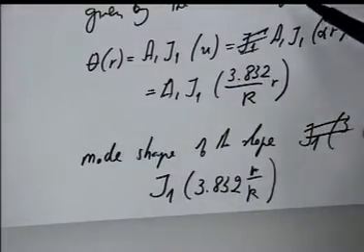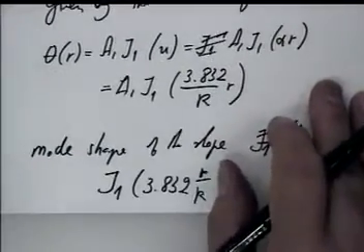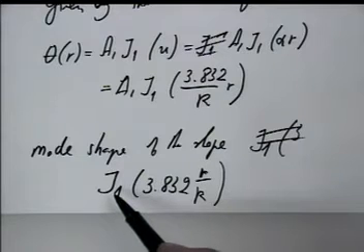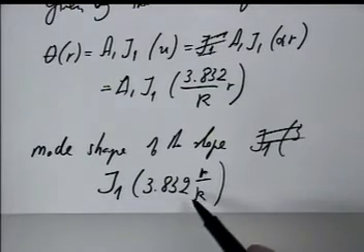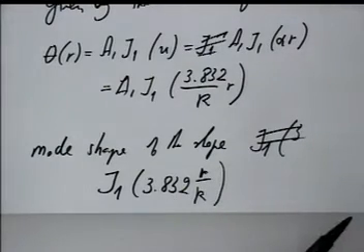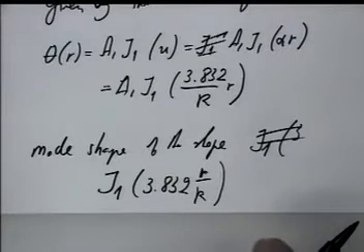So, mode shape is given as a transcendental function because that is an infinite series. For evaluating at any point, you should have an infinite series. We can actually reduce the number of terms, say to 100 terms, 200 terms, etc., depending on our wish. However, this is a transcendental function, and we got it.